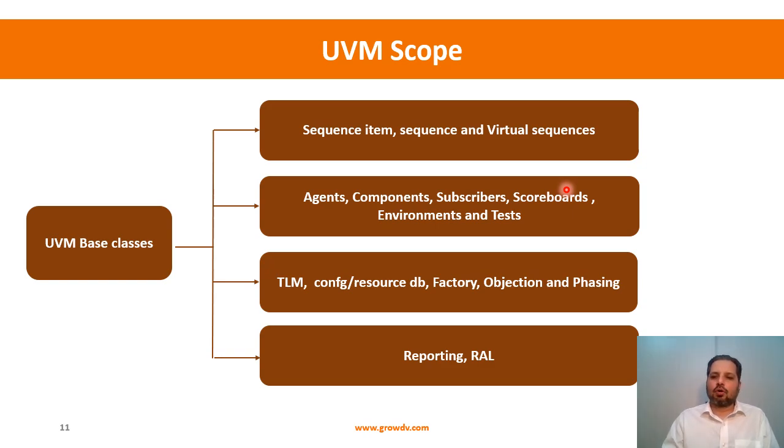Then you have these scoreboards. There are some base classes that can help you ease the process of building scoreboards. And then we have the environment class. If you remember, we were doing a lot of build, connect, and then run, finish. So we had a series of tasks that we had defined within the environment. The same thing, this will standardize and provide further. So there's an environment base class for that.